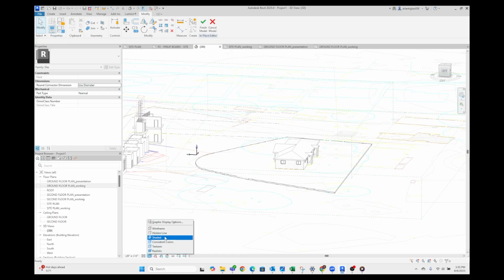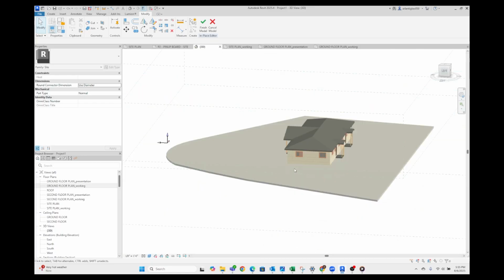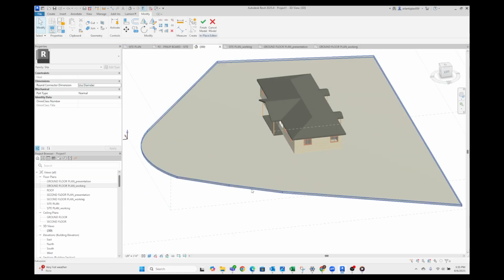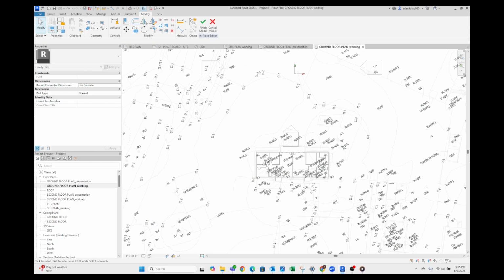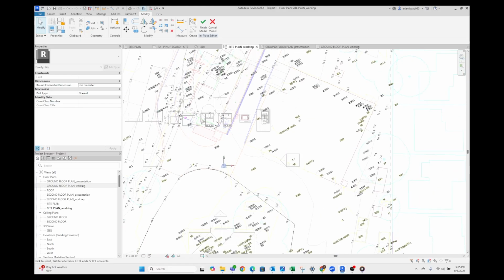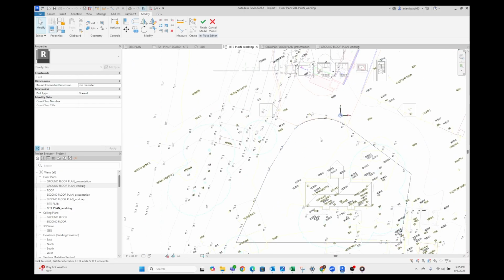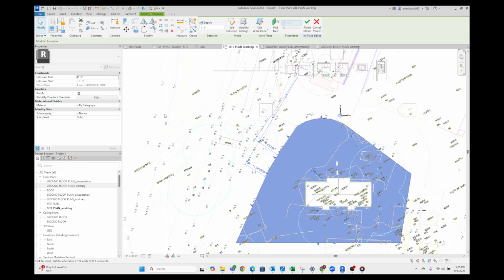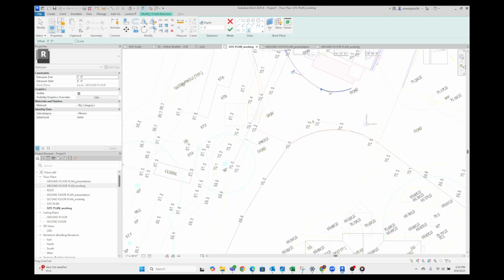And what that does for us is if I go into a different view mode, like consistent colors or the realistic tab, oh, I think I made a mistake doing that. You can see the color of the site. So I'm going to continue constructing the rest of my site by outlining the road, this animal barn here, and the green stuff. So just follow the steps that I did with this geometry, but I'm going to go ahead and press Create, Extrusion, then start picking the lines of the road.